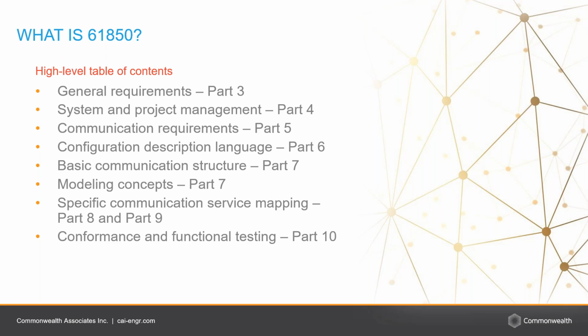So all these protocols and data abstraction on the logical device require a significant amount of configuration in order to put all the pieces together and have them work. So the SCL file facilitates this, since it allows the formal description of the relations between the substation automation system, the IEDs, and the substation equipment. Finally, part 10 defines the testing methodology in order to determine conformance with protocol definitions and constraints. Next slide.